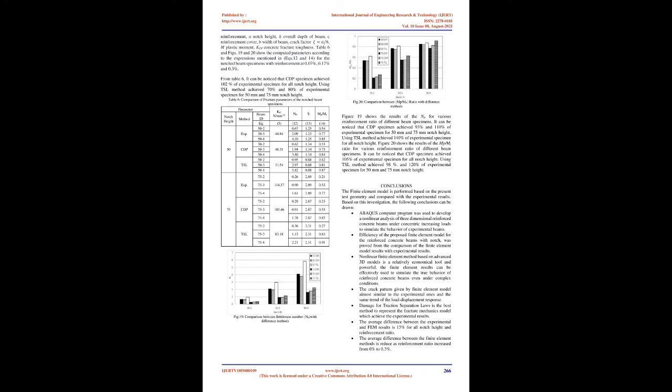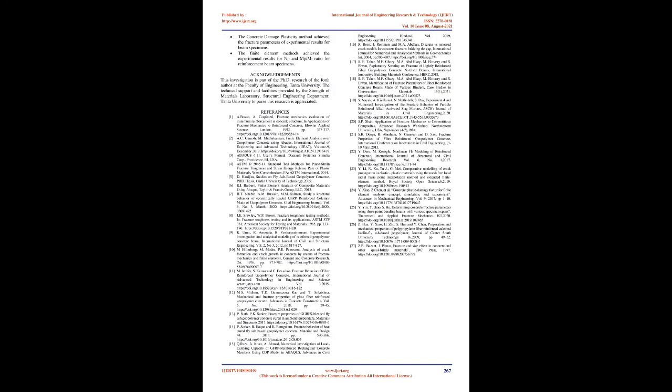Figure 20 shows the results of the MP/MF ratio for various reinforcement ratio of different beam specimens. It can be noticed that CDP specimen achieved 105% of experimental specimen for all notch height. Using TSL method achieved 98% and 120% of experimental specimen for 50 mm and 75 mm notch height.